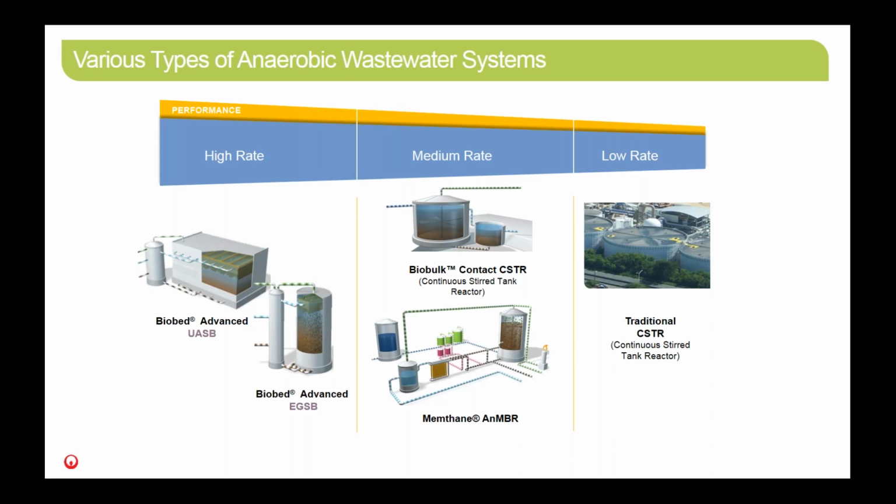Then you have medium rate technologies. These are your anaerobic contact processes, which typically include a mixed CSTR vessel and some kind of clarifier on the backside. That clarifier can be a traditional gravity settling clarifier, or it could be a DAF, for instance.